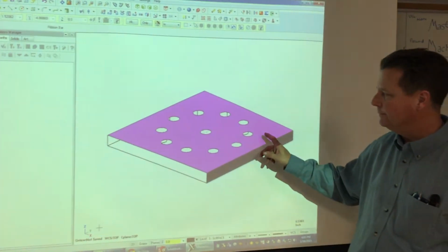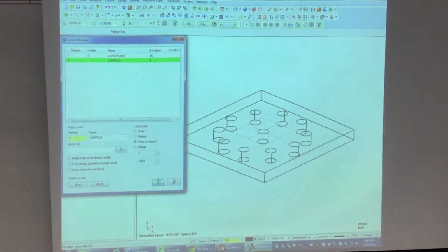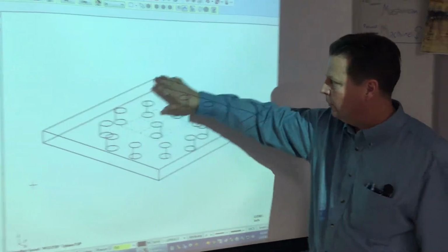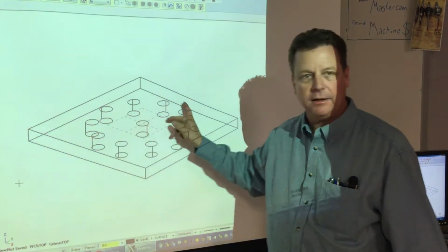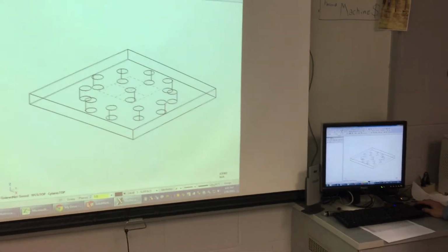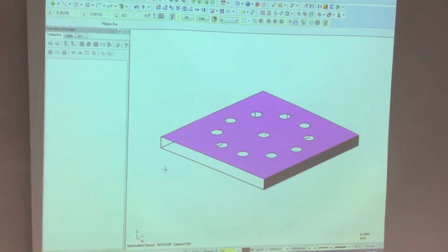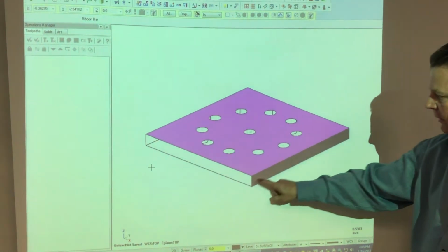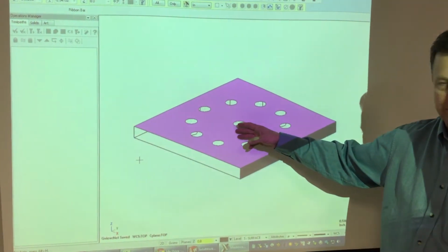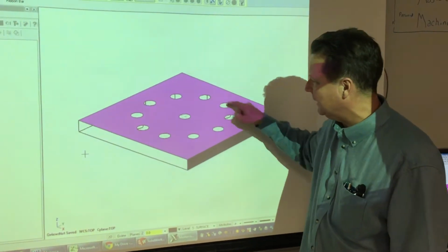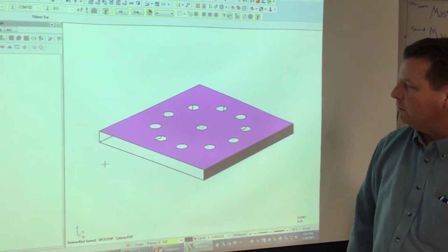with a black background. All right, I'm going to bring up this levels manager and blank surfaces. That is the wireframe. We drew all this stuff in one plane, and then we joined it down, and you can see the joining line there. Then we came back to our levels manager, and we learned how to create surfaces. And I created this one first in black. It's called Create Flat Boundary Surface. This is also flat boundary surface, but we picked these lines and then each one of the little circles in turn. And that's how we created our model.